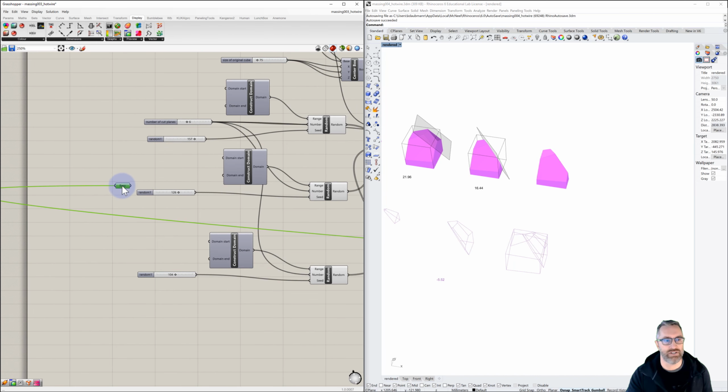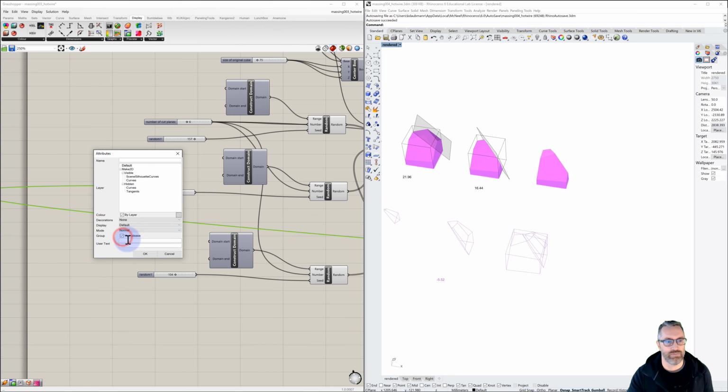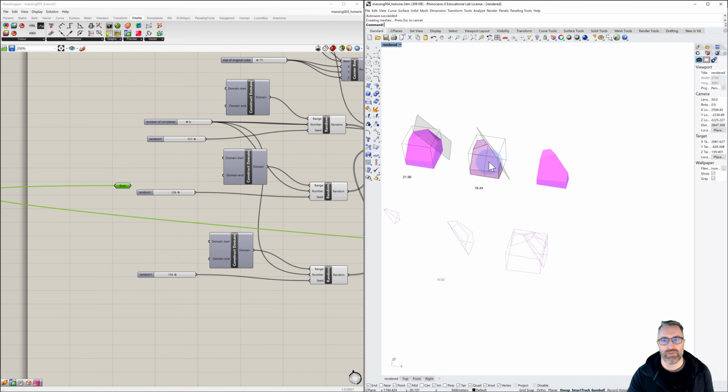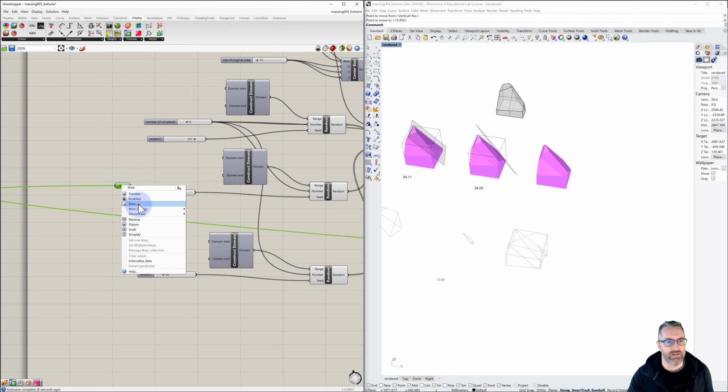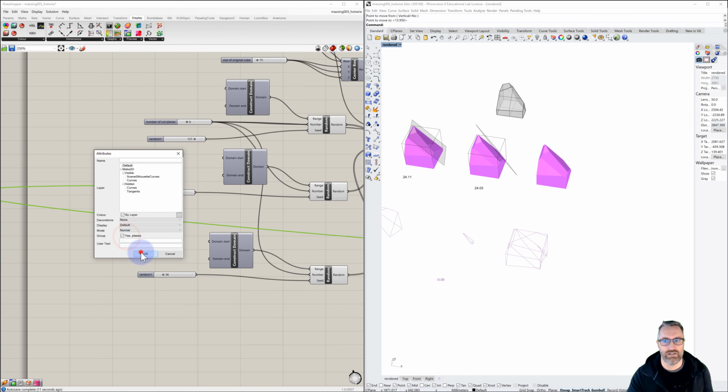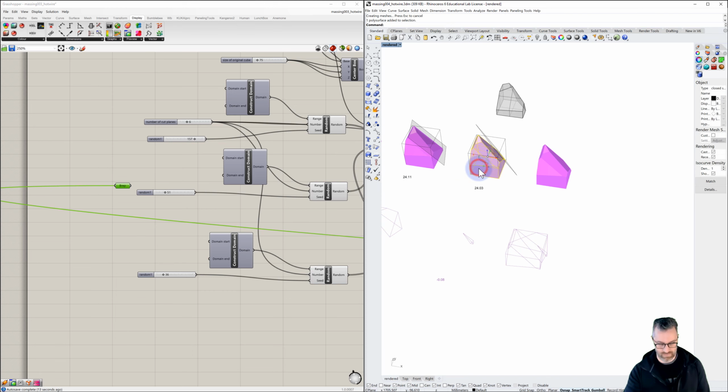If I change something, or let's say I'll bake this, I do want to group all of these and say, okay, we get this here. I'm going to move it to the side. Then let me make a couple of random changes. I'll join, or union is the right term, I'll union this together with another one. I'll select the BREP again, and I'll bake and group this one as well. Now I can move this over.